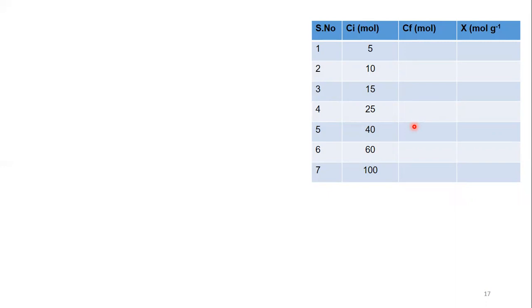If you are using an analytical tool like UV, send your samples for analysis. If you are using heavy metals, then send them for atomic absorption or for ICP. It depends on the pollutants you want to remove, which method is suitable for that. And after that, you need to find out the adsorption capacity.